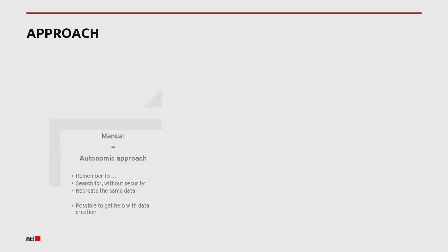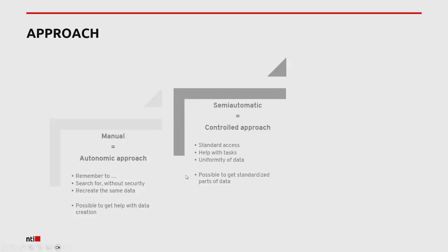So you can control the appearance of the PDF file, you can control the naming and the file structure of the PDF files. The second step could be the semi-automatic, which we also call event-based. So every time you save an Inventor drawing or change a property, check into Vault, whatever event you could imagine, can basically trigger the publish of a PDF file. It could also be a lot of other things that are triggered, but just to give you an example.